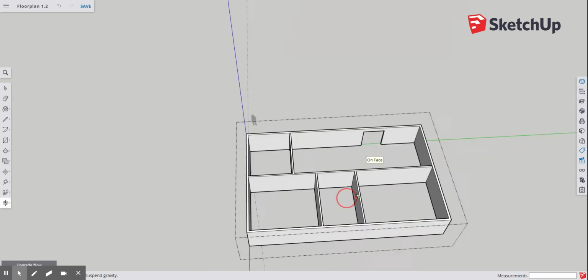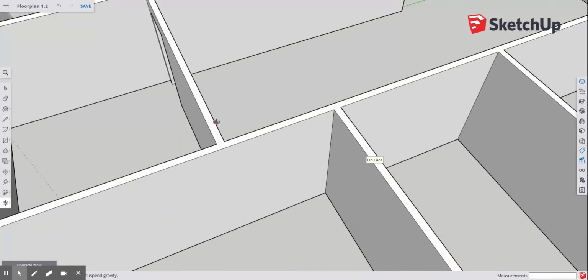Okay, now for this door, I have it 6 inches from this wall. So starting from the bottom, this direction, 6 inches. I made the surface at the bottom again. Remember, we could just delete that. Click it, go up on the blue axis, 6 feet, 8 inches. Go on the green axis, 2 feet, 6 inches. And go down on the blue axis.